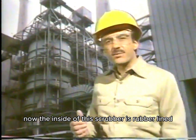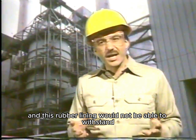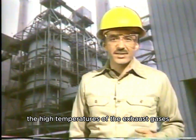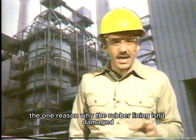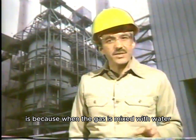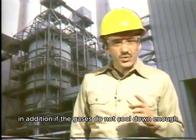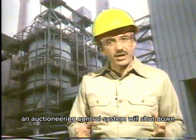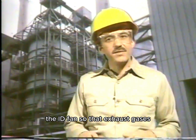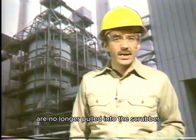Now, the inside of this scrubber is rubber lined, and this rubber lining would not be able to withstand the high temperatures of the exhaust gases coming into the scrubber. One reason why the rubber lining isn't damaged is because when the gases mix with water, they cool down. In addition, if the gases do not cool down enough to prevent damage to the lining, an auctioneering control system will shut down the ID fan so that exhaust gases are no longer pulled into the scrubber.